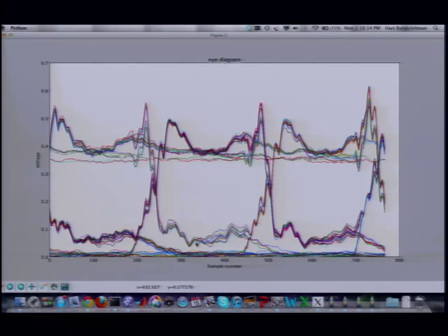The deviations might be noise, but the more structured parts of the waveform here match the structured part of the waveform here. And what you're really seeing is the loudspeaker reverberating through the room. You're all staying fixed, so the echoes are from fixed locations. The walls are fixed. And so what we're seeing is the step response of the room, in effect. And if you hit the room a little bit later, you get the same response, but a little later. Does this look like it's very linear? Would linearity be a good assumption for this channel?